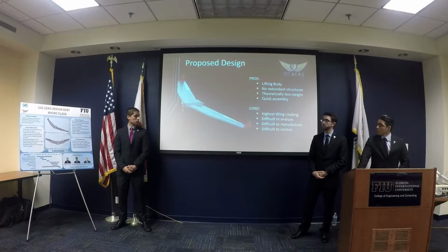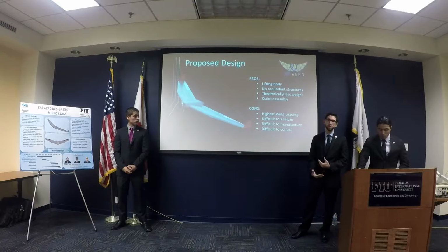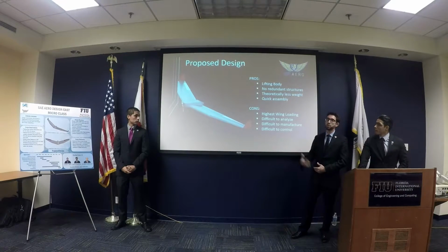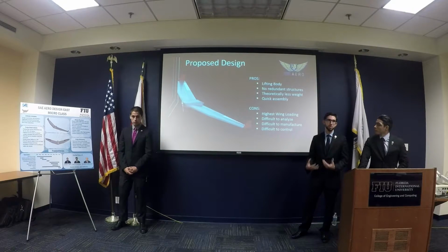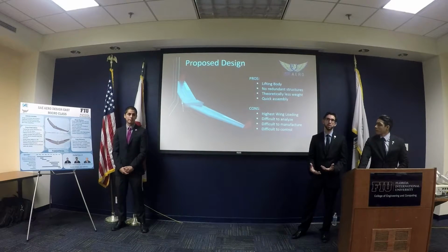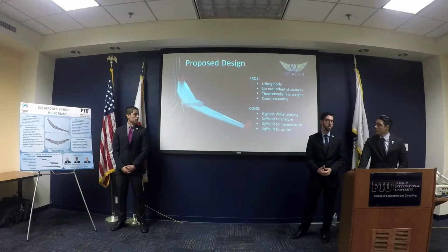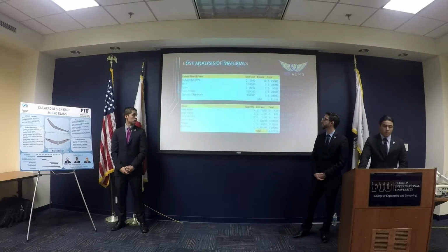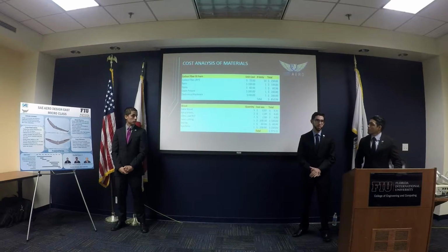One of the drawbacks of this design is that it's going to be very difficult to manufacture. Like I said, it has 3 different types of airfoils that we have to integrate, somehow model, and somehow manufacture. One of the pros, however, is that it's going to be extremely efficient. If we use the right choice of materials and the right manufacturing method, we can actually achieve something that is very light. Since we lack the horizontal and vertical stabilizers, it will be very quick to assemble. It's just a win.